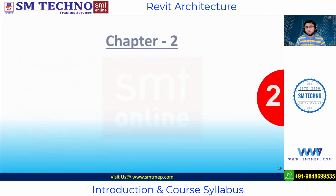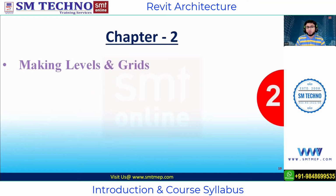Then again, next we have chapter 2, where we are going to see how to make the levels and the grid. Basically, we have two things. One is level and the other is grid. Levels we are going to provide especially for the elevation views, and grids we are going to provide in the plan to mark any kind of objects. It can be a column or any kind of equipment, so we have to provide the grid.